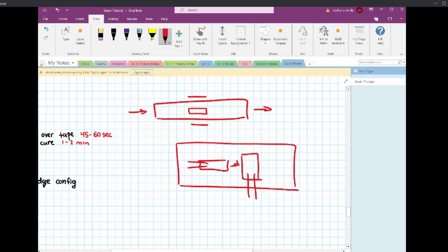And the way I think about this is you set up this one first because you want to see your axial and you want your principal strain gauge to be in the perfect position, and you kind of just place this one more or less eyeball it to be perpendicular because it's going to be dummy and you're not really going to see much in it anyways.